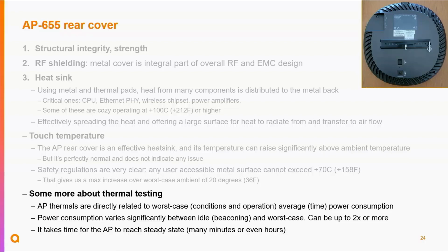And then a little bit more about thermal testing. The hardware team, Farhan's team, spend quite a bit of time making sure that each and every component on that board, when the AP is under max load conditions, is operating at the temperature it's specified for. And that temperature can be different for any component. A power amplifier has a very different temperature range than the CPU or a memory component.